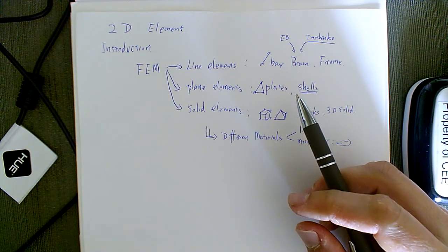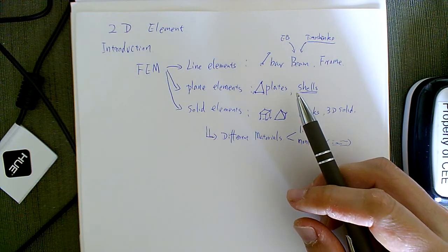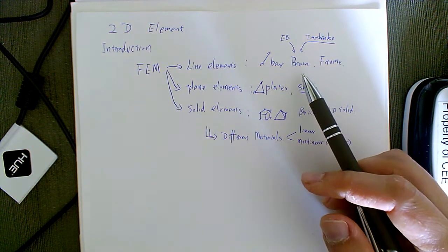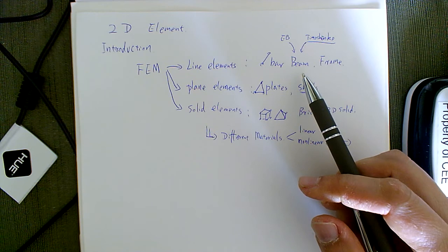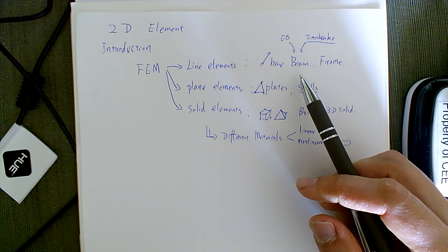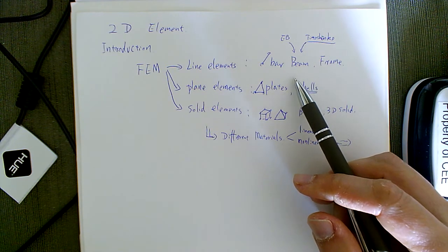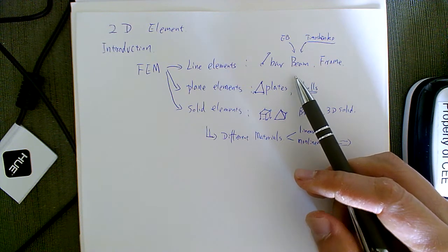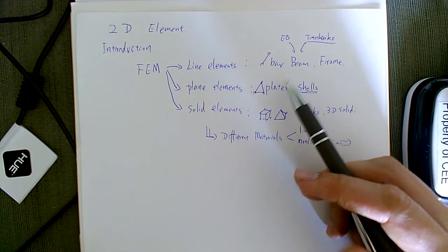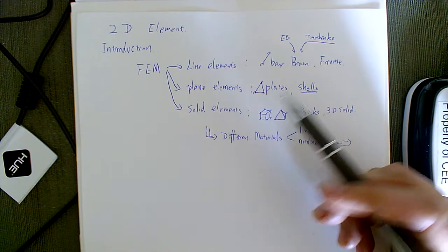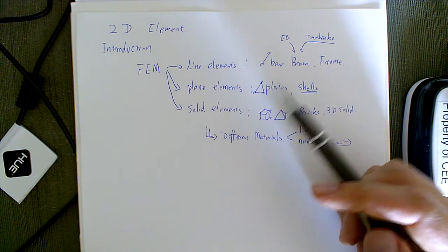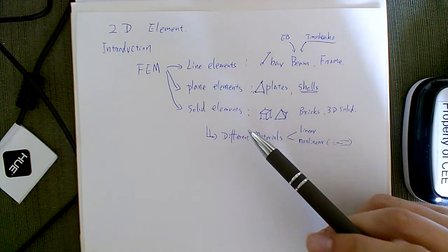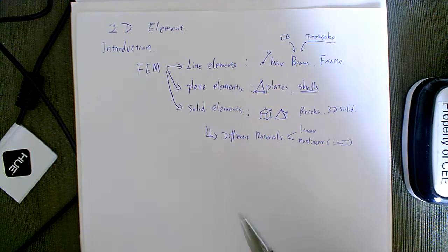That's just another displacement assumption. That's why when you see ANSYS or Abaqus, those pretty advanced FEM software, they don't just have one beam or one frame. They have beam 102, beam 503, whatever. They actually run out of names. But if you look inside the user's manual of that element, you'll be able to see what you're really getting, which kind of displacement functions are used.